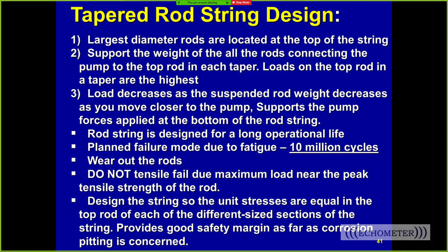QRod assumes that there's only friction on the rods as a function of the rod velocity, and that's the damping factor. If you're trying to model extra friction, then at the pump you can put a bigger plunger diameter in, and that'll make more pump load. But you really can't model. There's no place in QRod. TAM has the ability to add stuffing box friction to take out friction that's near the surface, but we haven't put anything in QRod yet to put in point mechanical friction load, so that's not available.